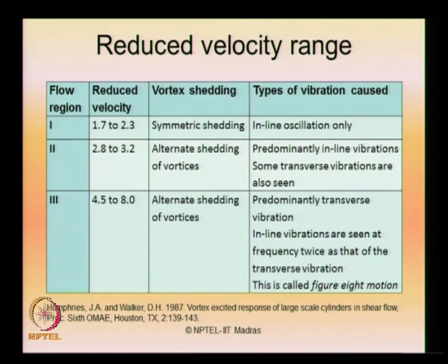So the frequency distribution in terms of transverse and inline vibration will cause a resultant response of vibration which we call a figure 8. This will result in a very dangerous type of failure to the member under flow region. So do not be happy when the reduced velocity is as high as 8, because the velocity may be low, but the amplitude of vibration can become very high, and can result in a very specific mode of vibration which can cause disaster to the members.